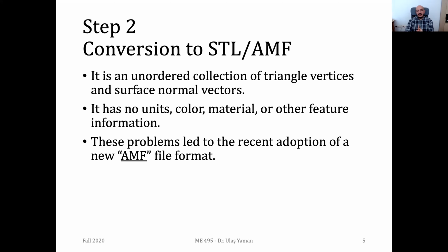Another thing, they are trying to come up with a file format which is universal for all the additive manufacturing processes. The format shouldn't work with just a single process, like fused deposition modeling or stereolithography. It should work with any additive manufacturing method. This is one of the motivations of the additive manufacturing file format. But still these days, we have this problem. STL is still a de facto standard.